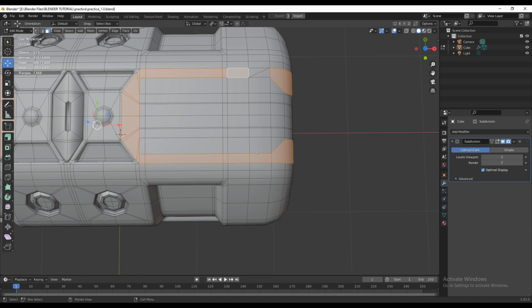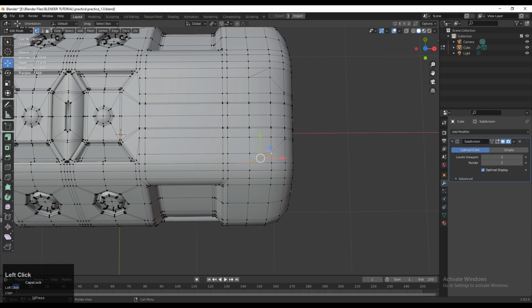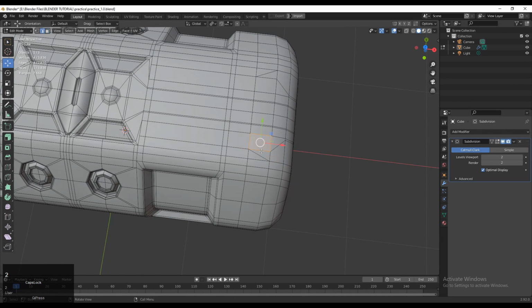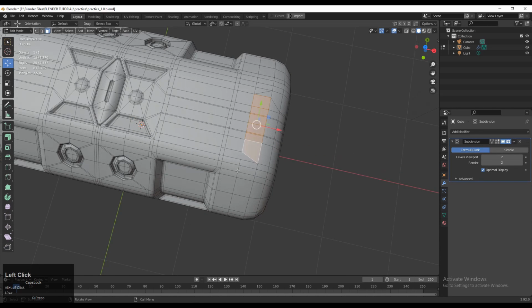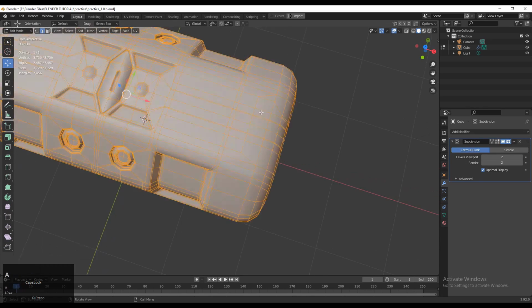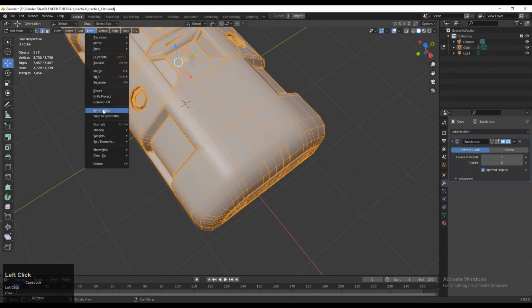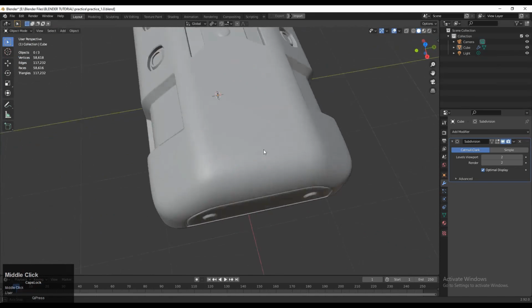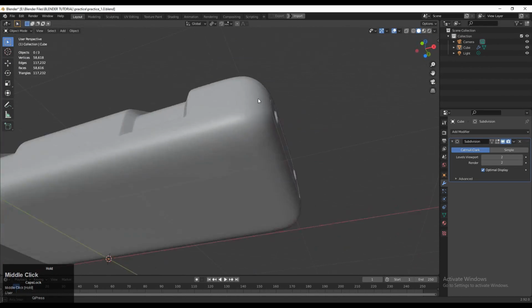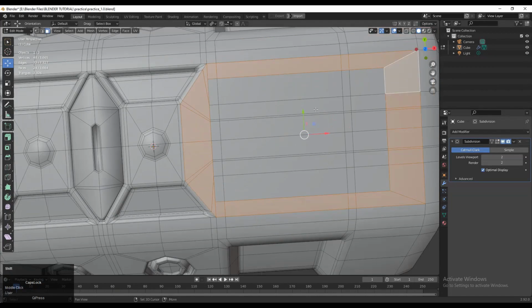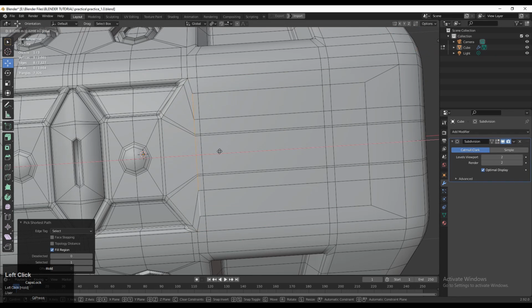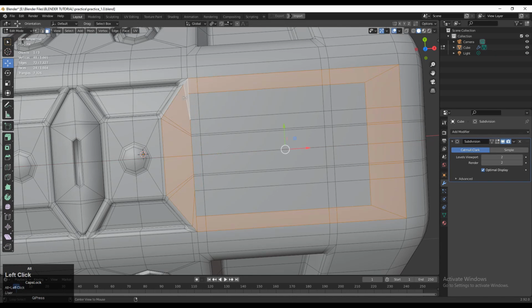So select the vertices, right click and then connect vertex path and then create a cross connection like that. You can see the cross connection also. And then you can dissolve a few edge loops, and then you can create that loop structure. So simply you will get a different face loop structure. So we have got that there, and make sure you don't create such a structure on the curved surface. It is totally on the flat surface, so we can easily use different operations on it.